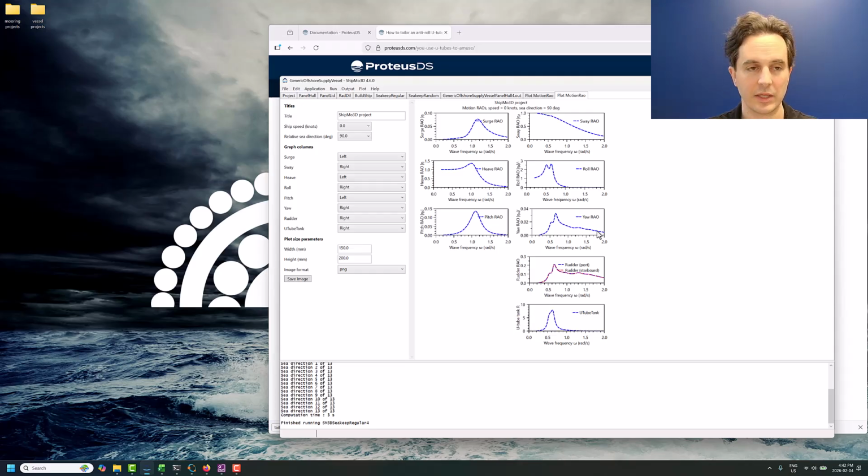So anyway, the main point that I wanted to show was just to get this idea that if you can get as big a tank in place as you can fit in the ship, a quick way to tune it is playing with that duct height. Faster to make it taller, slower to line it up to the natural roll period. Make the duct smaller, right?